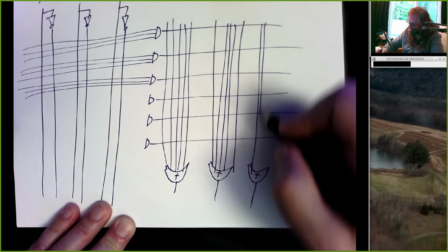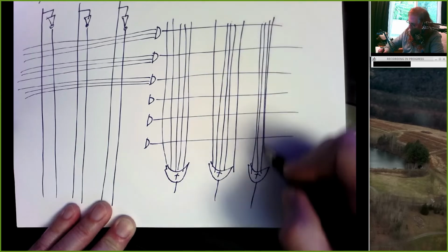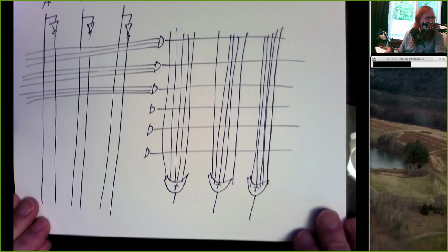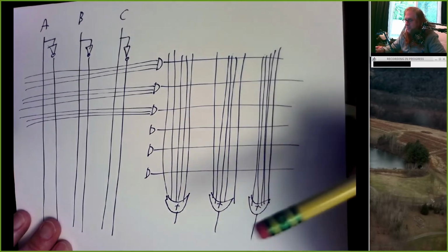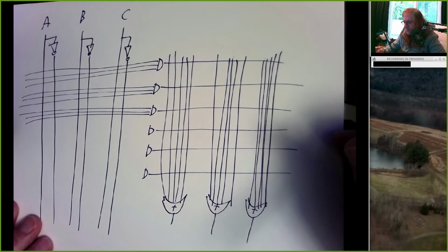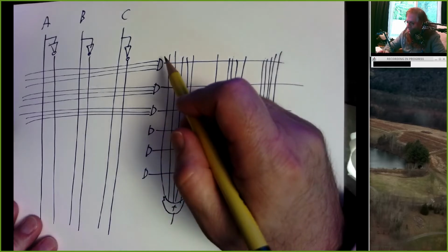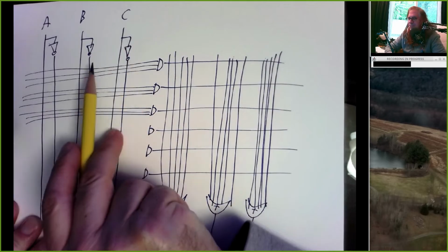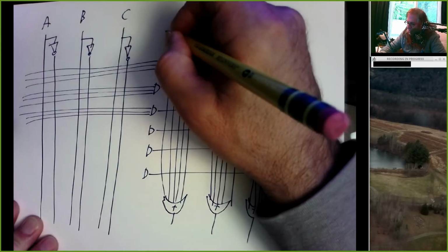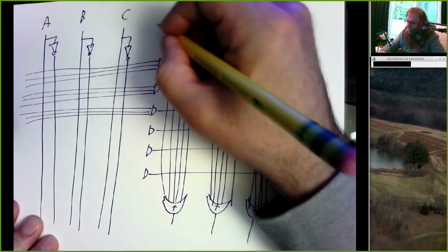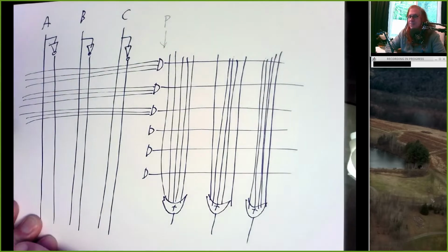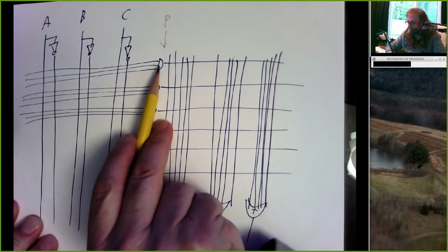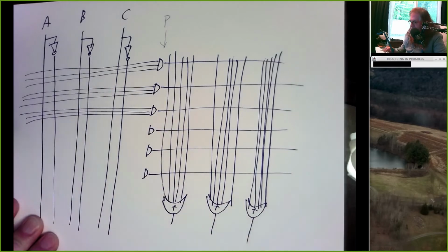And so on. And this is a completely general template now for sketching a circuit diagram. I can make each of these AND gates any combination I want of A bar, B bar, C bar. In other words, I can create any product term or any min terms that I want, by just choosing which inputs should get connected to the inputs of this AND gate.